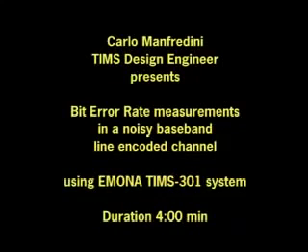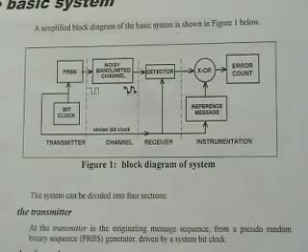Bit error rate measurements in a noisy baseband line-encoded channel. Following this block diagram, we will firstly model a line-coded transmitter consisting of a pseudo-random sequence generator as the data source, which is then line-encoded. Next, we will model a band-limited baseband channel with added noise.